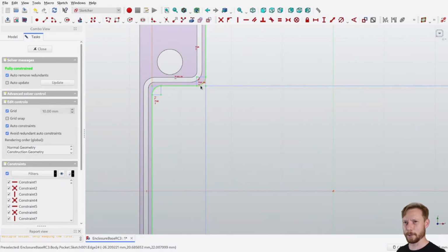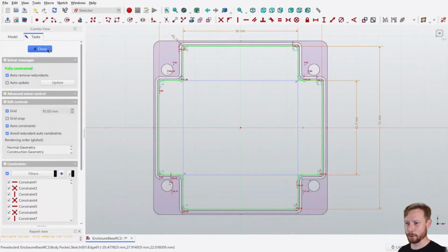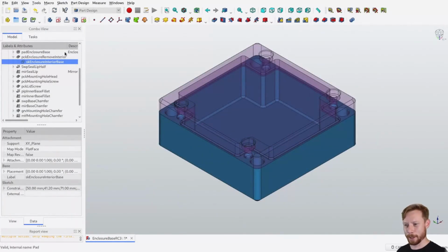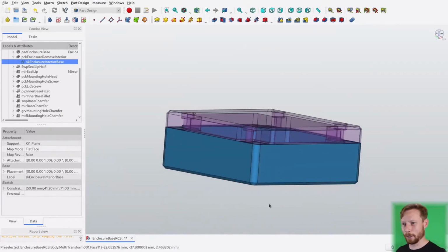This also alleviates a lot of FreeCAD's problems with fillets and sketches, because anything that you can draw in the sketch, you can pad or pocket. That doesn't solve the how do I put a chamfer on the top and bottom here? I can't put that in the sketch. Well, I model them manually. I use the additive and subtractive pipe tools to do so.